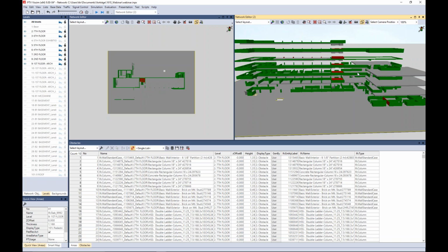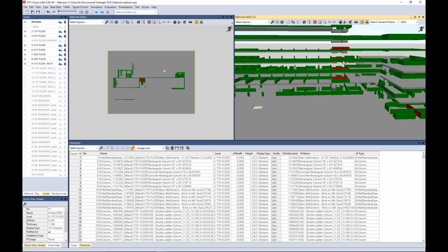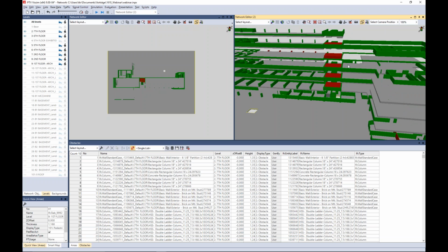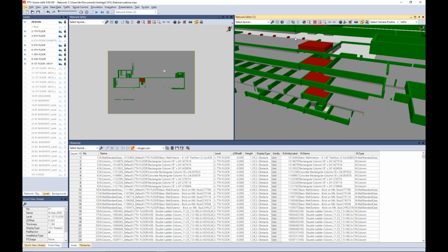In IFC these exist, so this is modeled in Viswalk with the combination of an area and an obstacle, and then such obstacles which in fact are holes are shown in orange. And the last color which is used in the converted file is red, and red means that the converter realized there is an issue here, and this issue can be either that in the IFC file something does not match exactly the IFC standard format.